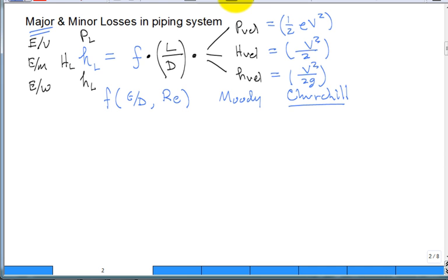All you did was what we talked about before. Usually we think about starting Bernoulli's equation in the form of pressure. Then we divide by density, or multiply by 1 over rho. There you go. You went from pressure to another form of some conservation of energy statement, basically from energy per unit volume to energy per unit mass. And then if you went and divided by 1 over rho g, you went from energy per unit volume to energy per unit weight.